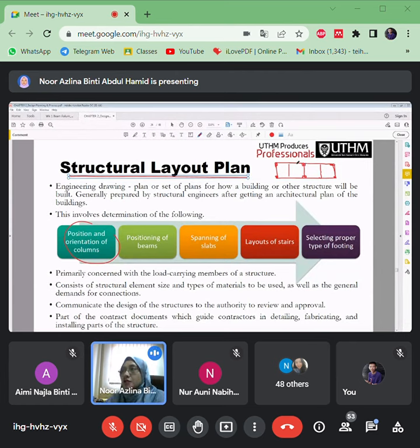So that means the reinforcement will be continuous to this column, and this reinforcement will continue to this column, and this reinforcement will continue to this column. It's back to the basic thing of stability. You have to tie it, to make it firm and strong. So the tip is, the column should be placed at the corner or at any intersection.